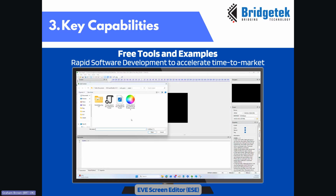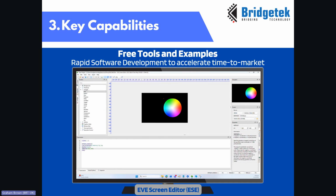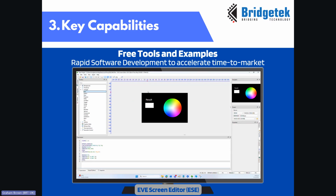The next toolchain we have is our Eve Screen Editor toolchain. Now, this is a screen emulator tool, which allows you to view the raw embedded video engine commands, which we call display list or coprocessor commands, in its window here. This allows you to see what commands exactly are required to generate a screen on Eve and can be utilized with USB to SPI converters to attach directly to development modules or your application module.